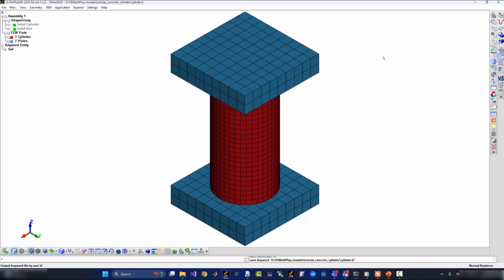So I'm going to now, first of all, define the curve. The curve gives me a function of time, basically. So I'll define a curve which gives us a monotonically increasing function of time, which is equal to 0 at time 0 and 1 at time 1. This will allow us to run an analysis up to a time of 1 where we monotonically increase the magnitude of displacement from 0 to a target value, which won't be 1, but we'll see how we will do that.